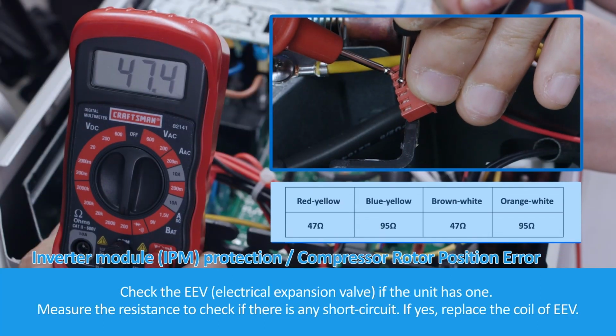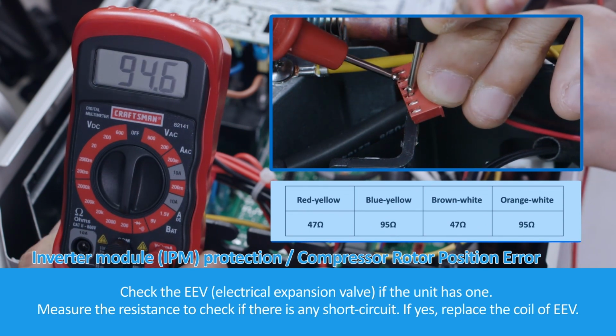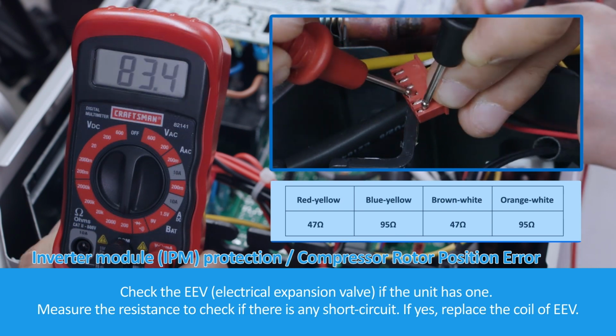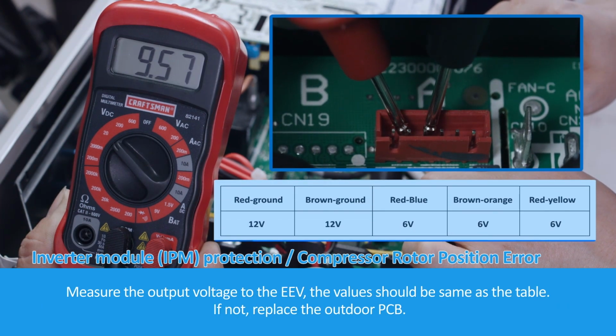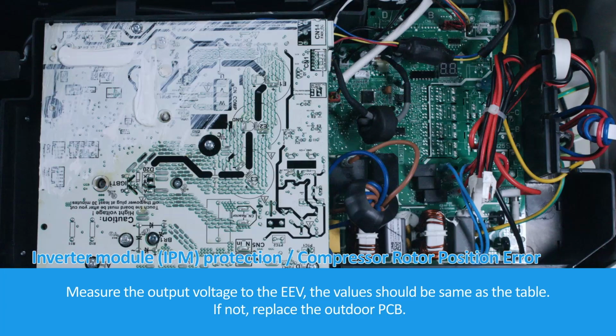Check the EEV, electronic expansion valve, if the unit has one. Measure the resistance to check if there is any short circuit. If yes, replace the coil of the EEV. Measure the output voltage to the EEV. The values should be the same as in the table. If not, replace the outdoor PCB.